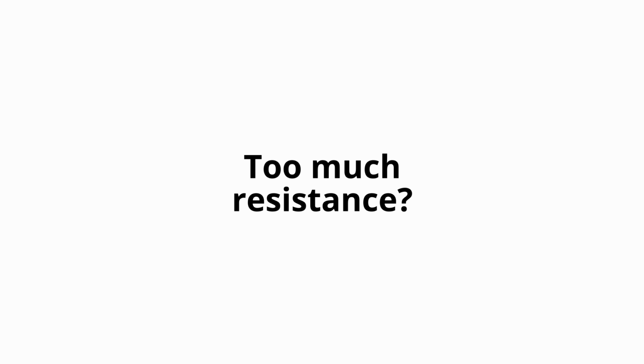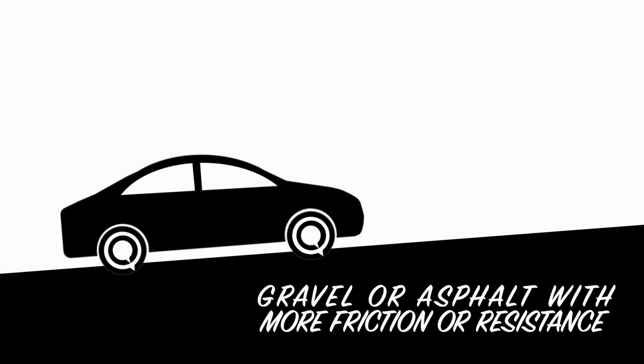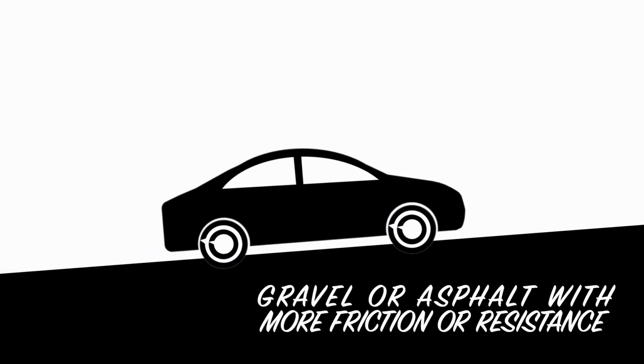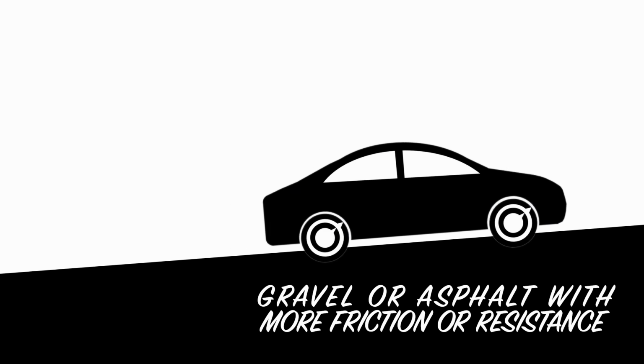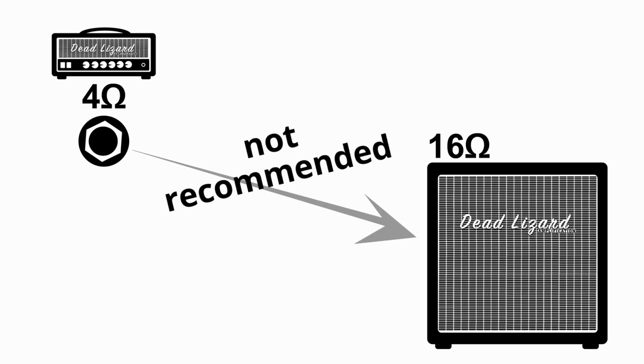How about, what if there was too much resistance? You could think of this like driving up a steep hill, not very efficient or optimal for the car nor its engine, at least not in the long run. Okay, the hill ain't that steep, but you get what we mean. We can think of this as connecting an amp's 4 ohm output to a 16 ohm speaker. Depending on different factors like how loud you play and for how long you play for, this might damage your amp.